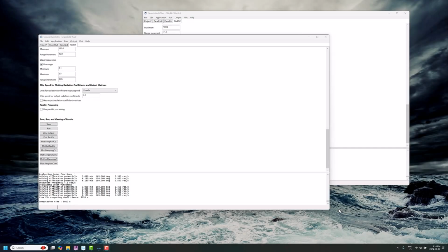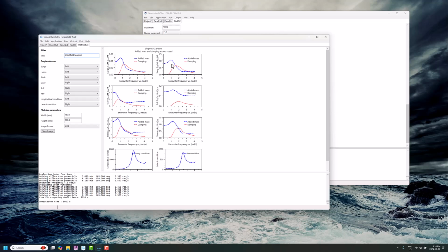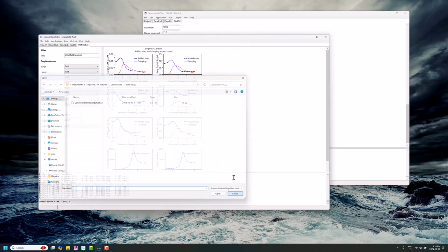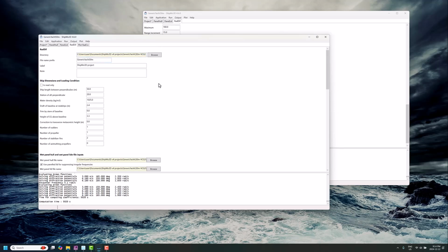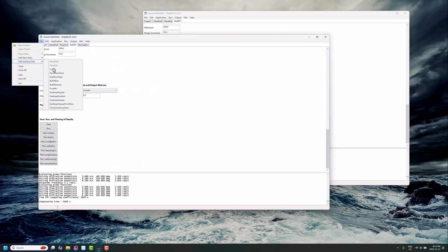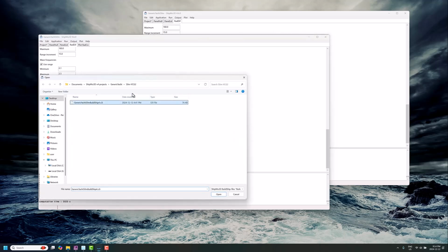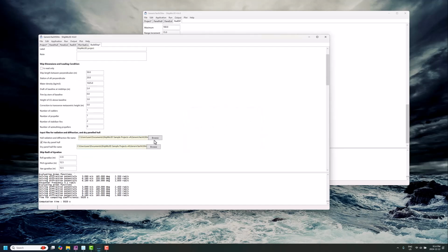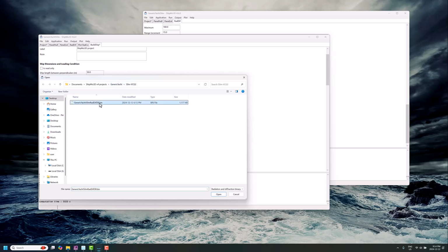Okay, those radiation and diffraction calculations are done on both of them. You should see something pretty similar for both of them, as well as on the nominal VCG one. Everything looks pretty good there. So we need to continue for both of these to finish up the ship model. Let's make sure that we are looking at, okay, this one is VCG2, so we will keep working with this one. We'll add build ship, VCG2, and we have to make sure that we have the right radiation and diffraction database calculated for that.